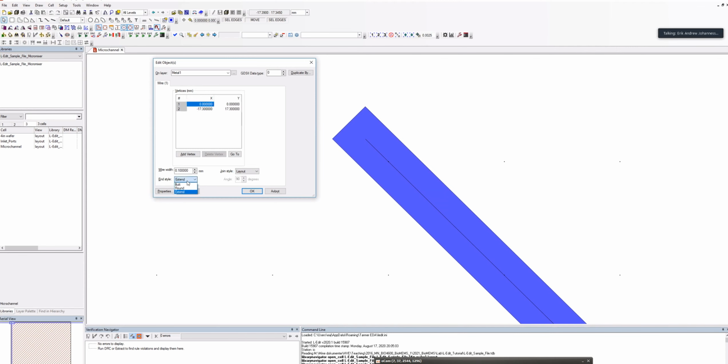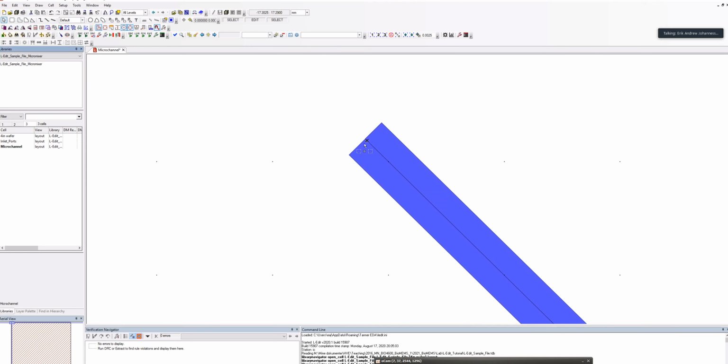You can choose to have a butt end like this. That means that it doesn't extend at all. It just goes exactly to the end. So if you're going to make a design that's completely accurate, then you should choose a butt end, because now it's adding another 50 microns on top of the length. So it becomes 50 microns on either side. So it becomes 3 millimeters, 3.1, isn't it? No, so it becomes 30.1 millimeters, since you're having extended ends.